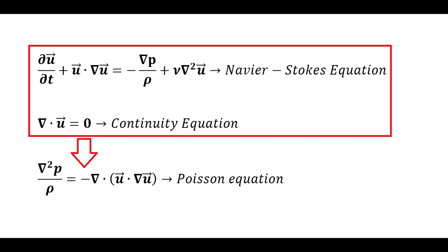When you try to modify the pressure field along a wing, an airfoil in this case, or when you try to modify the velocity field, you will alter the other. So you can't modify the pressure without modifying velocity and vice versa. So what generates lift are both velocity and pressure.